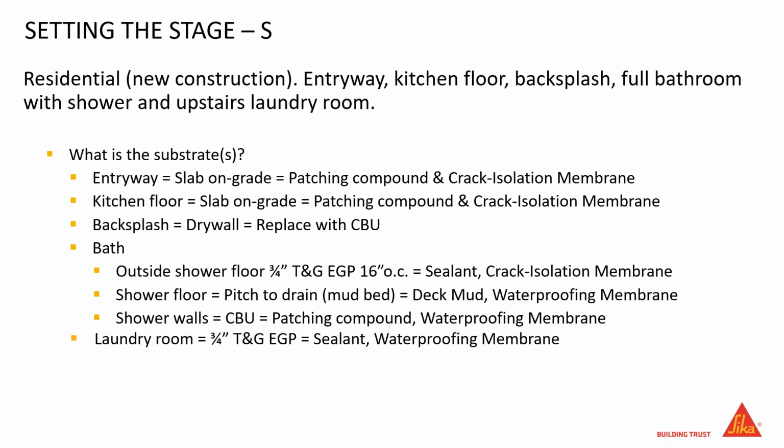Shower walls, CBU. So again, it's a cement backer unit. We're going to use a patching compound if we need to bring that wall into tolerance. And I think a lot of people forget that those walls still need to carry that same stringent tolerance of 1/4 in 10 or 1/8 in 10. So we need to look at that. We might need a patching compound to fill in those low spots in that wall to create a perfectly flat wall. And then on top of that, we're going to put our waterproofing membrane over that patching compound on the walls just for extra protection.